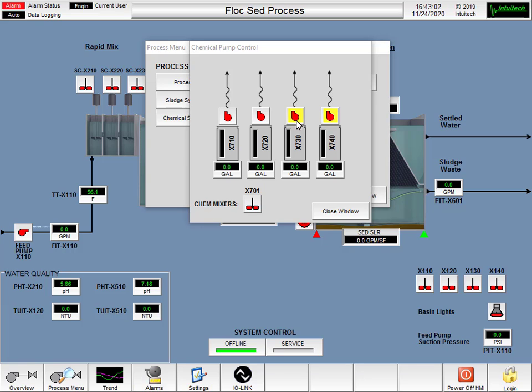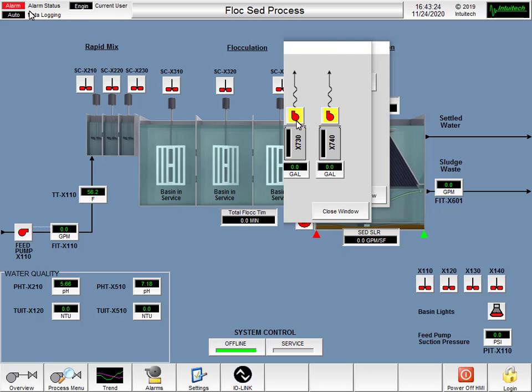The last item is these chemical pumps are peristaltic pumps. What this means is the pump head physically compresses and moves the tubing that goes through it. The downside of using this type of pump is that the tubing will eventually wear out. Make sure to regularly check the tubing and to shift or replace the tubing as needed.